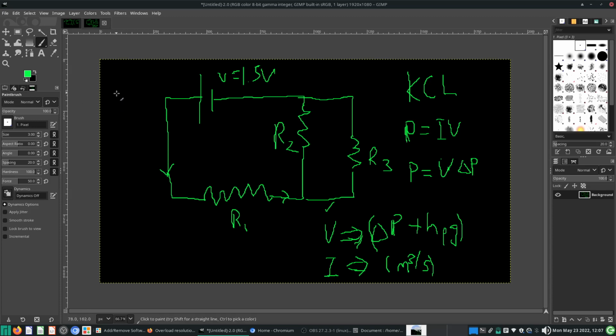Okay. So if you think of work done in a gas, usually we integrate PdV. Okay, this is a thermodynamics thing. Work done equals PdV. So PV is a unit of work, and then this thing is volumetric flow rate, so it's a volume per second. So both of these, when you put them together, will also result in the same power units being here. So that's why it is nice to have delta P kind of analogous to voltage, and volumetric flow rate kind of analogous to